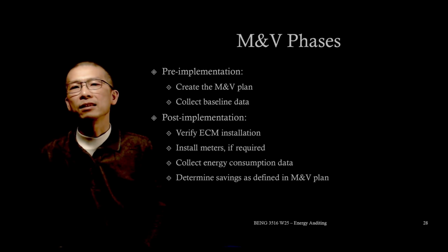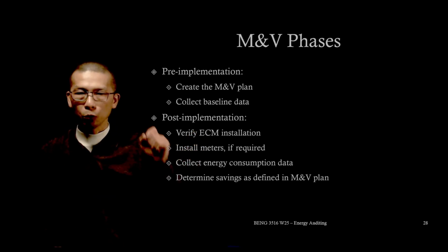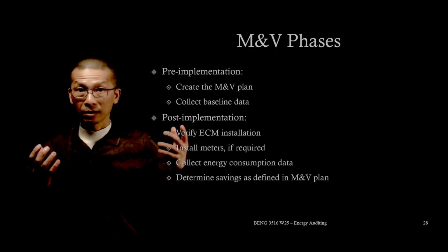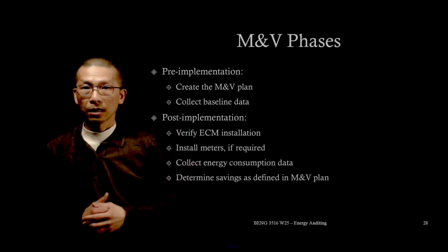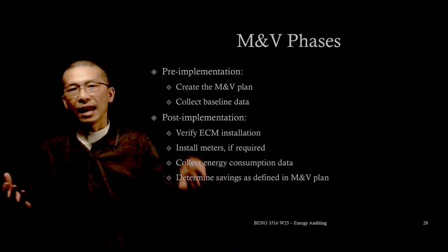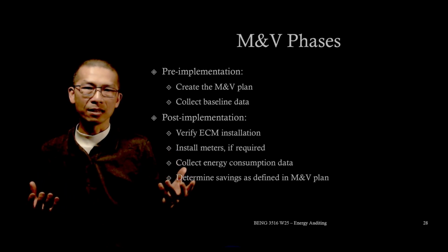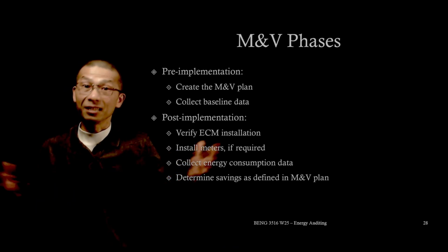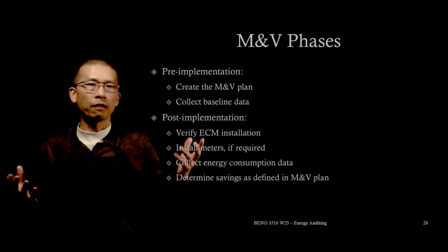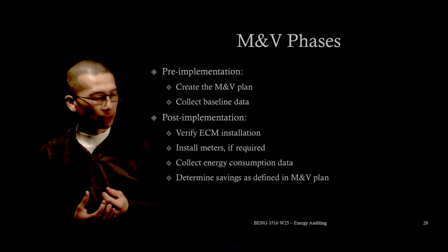Then there is the post-implementation phase, which first verifies the energy conservation measure installations. Ensure the energy conservation measure has been properly installed and it's operating as designed, as expected. So this can involve, say, on-site inspection, performance tests, right?